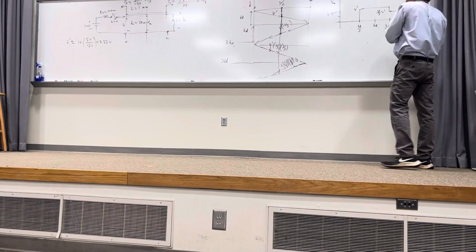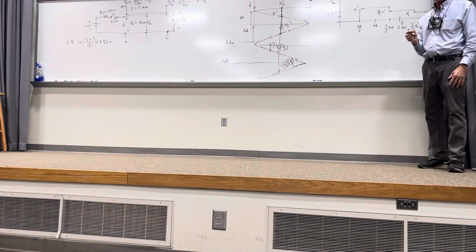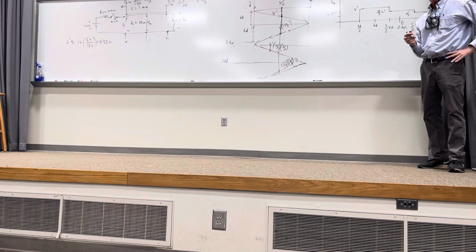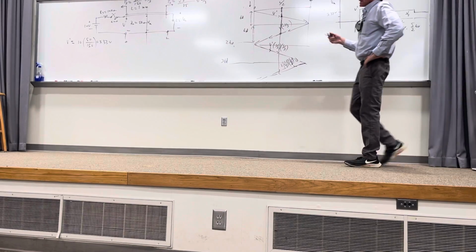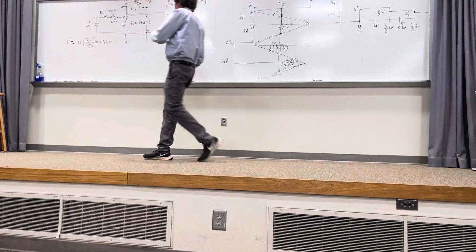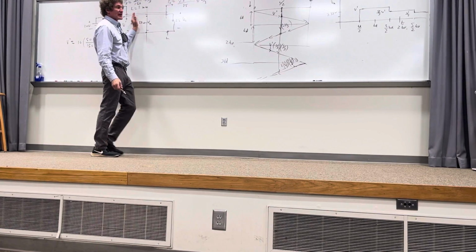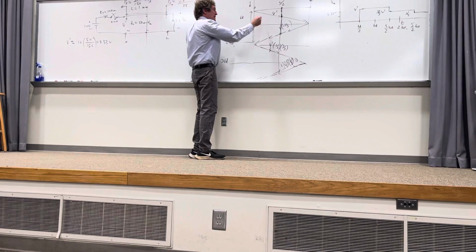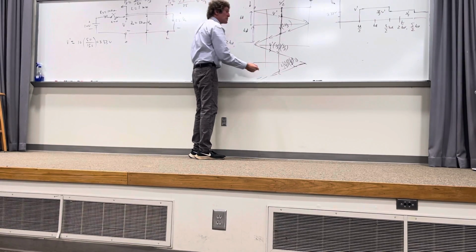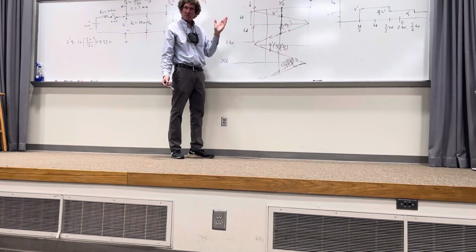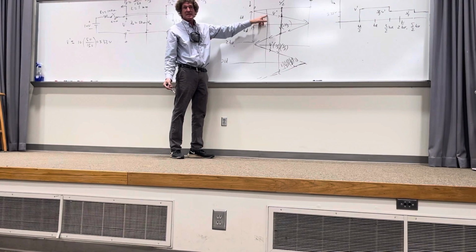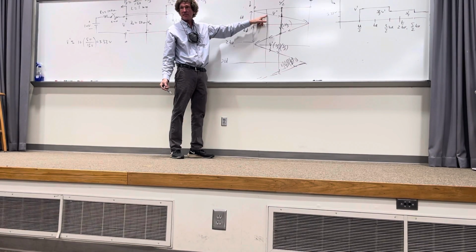We could keep going on and on about this, but you all see how to get a bounce diagram for the voltage developing in the middle. It would be the same at any point. If it was going to be at only a quarter of the length down the line, then you would draw a line here, and you would do the same thing. Only now, the first change would occur at what? TD over 4, correct class?